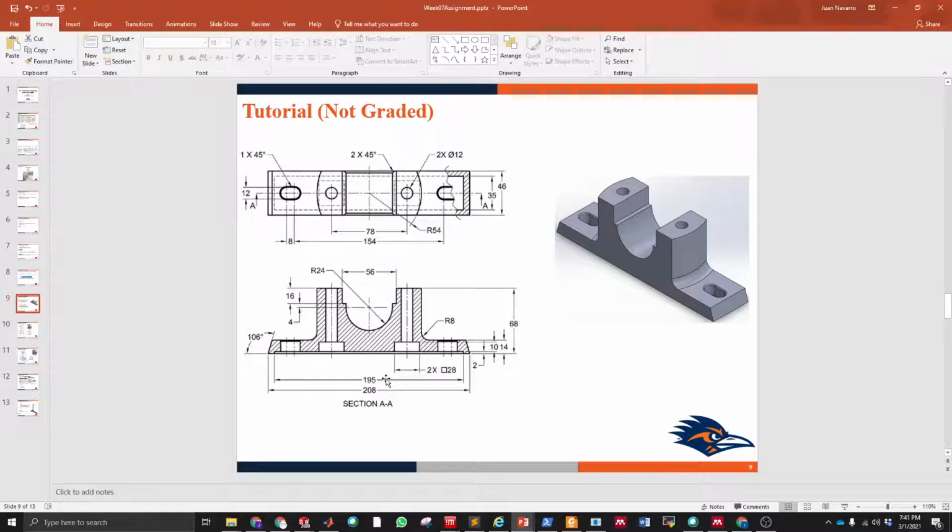We learned how to do extrusions and cut extrusions, and also how to extrude or cut a revolution. We also did the fillet here and the chamfers in the two slots. And using one single sketch, how to produce several cuts within the material. Also, we learned how to have a viewing section, as we did in this section AA.